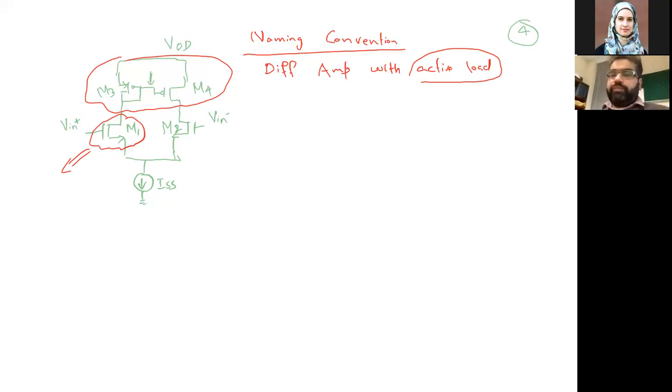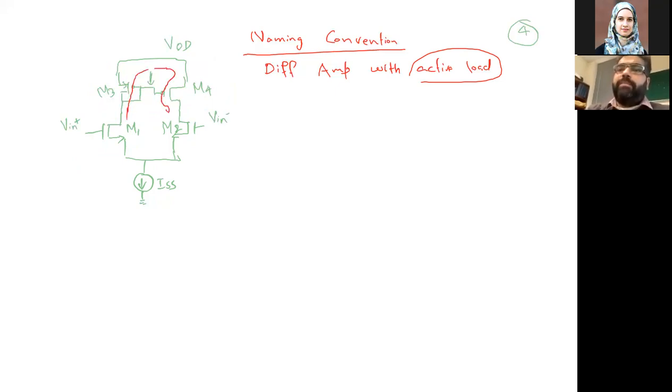The second thing, which is very important. Now we need to see there are two behaviors which we already saw. If I1 changes from here, this loop which I'm drawing here in red color is going to have an impact. If V in plus goes up, what's going to happen? The current will increase. We all know I plus delta I will happen. So there is some plus delta I. Because of that plus delta I, the current will increase here, and as we just saw in a phenomenon, the V out will go high. So V in plus increasing makes V out go up.